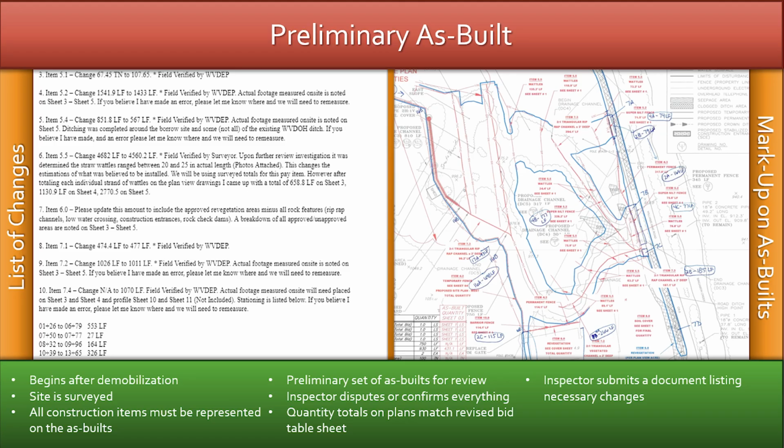As-Built Review and Acceptance starts after the demobilization of equipment. This process takes at least a couple of weeks and may extend to a couple of months depending on the urgency of the contractor. Typically, around the time of substantial completion, the contractor's surveyor begins marking all the installed construction items and documenting the same baseline information that was provided in the pre-construction survey and cross-sections. A complete list of as-built items can be found in the construction layout portion, section 2.0 of the specification book.